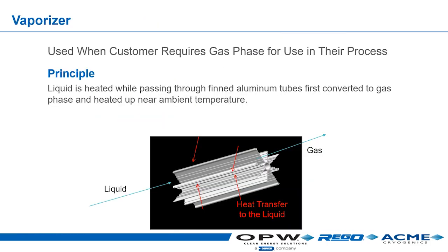Those are our products by number series that get used where. Talk a little bit about vaporizers. So you see how that vaporizer is shaped? It's a star fin shape. You see the tube in the middle of it? I just want you to remember we talked about heat transfer. The liquid product stays in the inner tube right down the middle, right? So the way this is designed, this is the right material to absorb heat. So the heat just gets captured in these fins, and as the liquid is running inside the tube, it's getting warmed up and changing from a liquid to a gas.